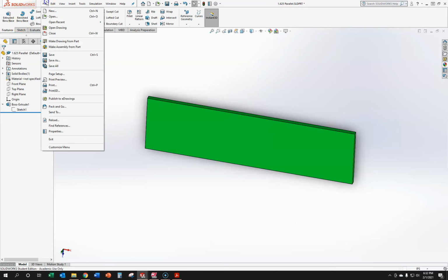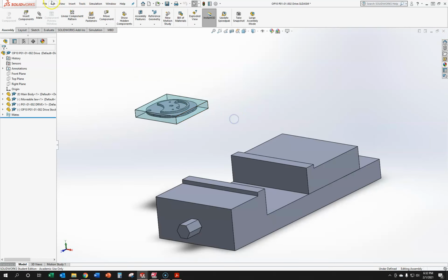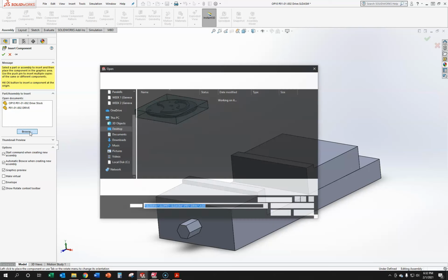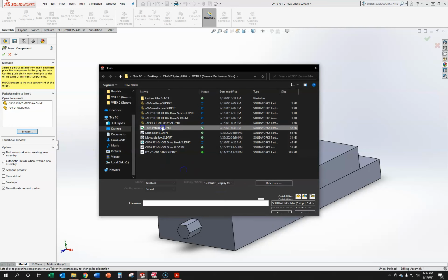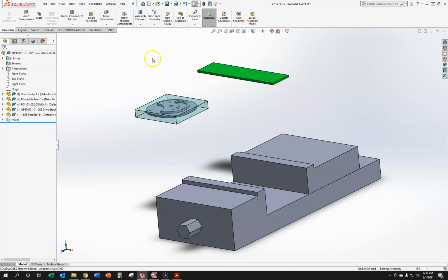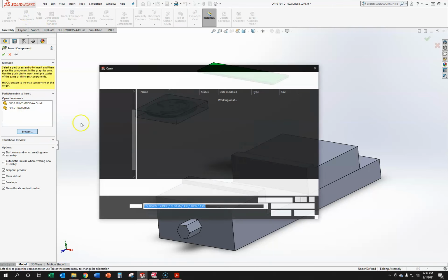Exit and save. And I'm going to close this one again because I don't want to accidentally bring in the wrong one. So now that I'm back in the assembly here and I know what those dimensions are correct, I'm going to insert again, go to Browse, and grab the 1 5/8 out of my project file. Again, not out of my fixturing file, the project file. We're going to go ahead and need 2 of these. So I dropped one. I'll go and browse and get the second one.